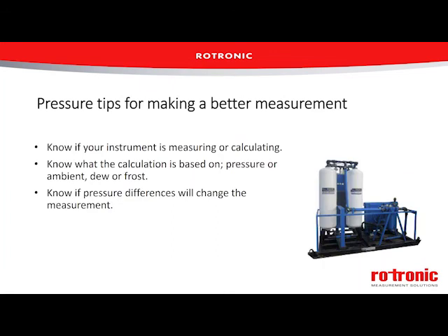Basically, I guess bottom line when it comes to pressure, if you have a relative humidity sensor measuring relative humidity in an open room or an open chamber or some type of outdoors open environment, you don't have to worry about pressure. The sensor is going to give you a true relative humidity. If you're calculating one of the absolutes, then as I mentioned earlier, you have to make sure the pressure, usually barometric pressure, is accurate depending on where you're located, what elevation basically.